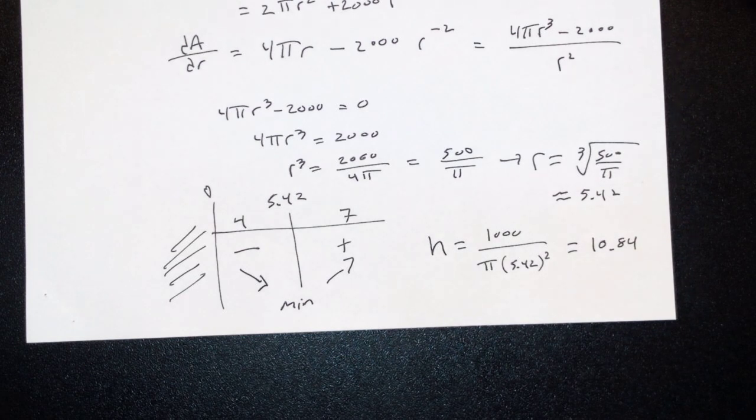Now you'll notice this assumes that I'm not worried about any materials strength or anything like that. Soda cans, energy drink cans, they're not round like this with flat tops and flat bottoms. What do you see as you get closer to the top or closer to the bottom of the can? Bunch of curves, right? Those curves and the curve on the inside of the bottom are designed for the pressure, because the contents of that can are pressurized, right? I need to take that into account.